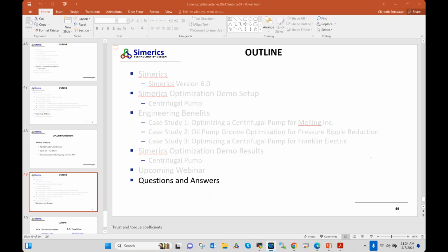One is that in our cavitation model outputs, we have some terms which can visualize the power. That power is based on the velocity change and the pressure difference. So based on that, there's a power term that we have. The power can give you some quantitative idea of how much potential there is of damage. So we have some threshold above which damage is likely.